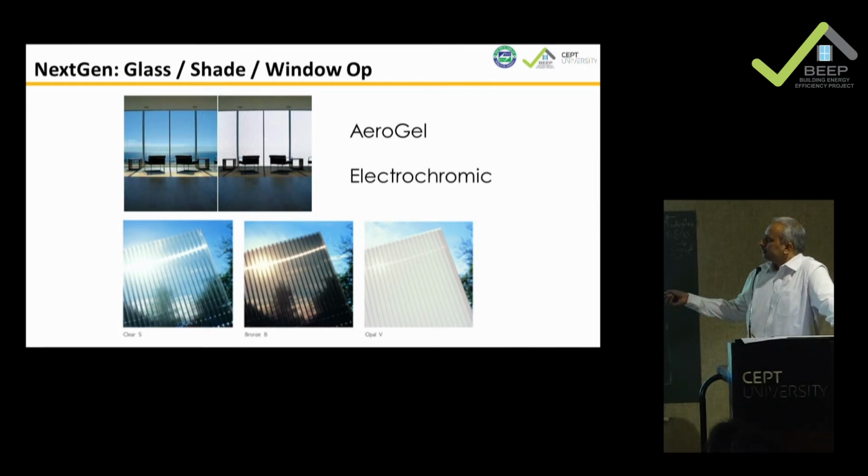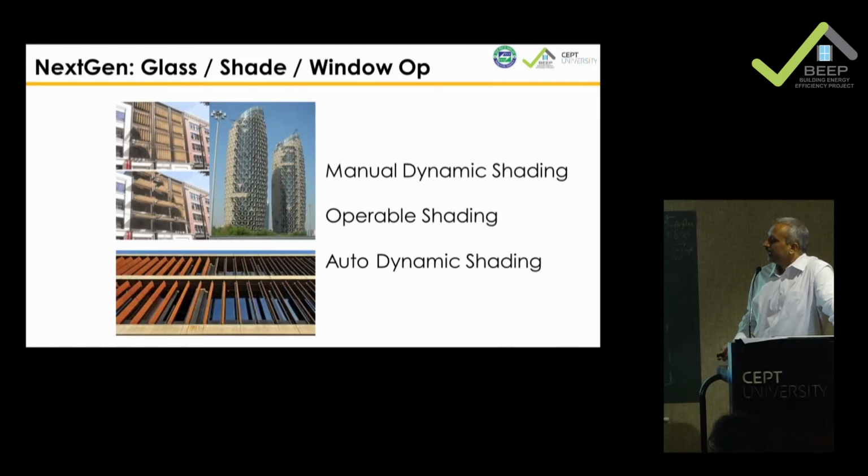Or we have started getting electrochromic glass. Depending upon outdoor radiation, the glass tinting will change. If the outdoor is too bright, it will become sort of opaque or a little. So your VLT will keep changing depending upon what's there outside. And that's what Boeing 787 and Airbus 380 and 747 and other people have started using. So there's a sort of advancement which we have in glass.